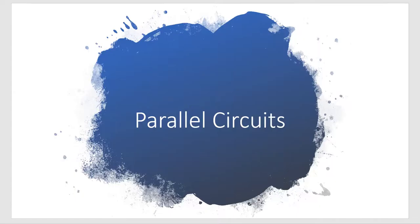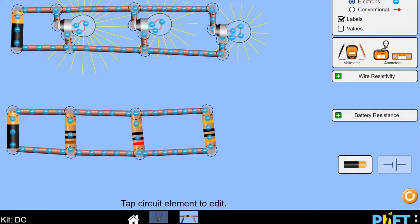In this lesson, we're going to talk about parallel circuits. Let's use these two examples. So as you can see, we have a power source. The electrons are going to come out the negative side, travel down this path here, go across whatever the load is, and come back on this side here.